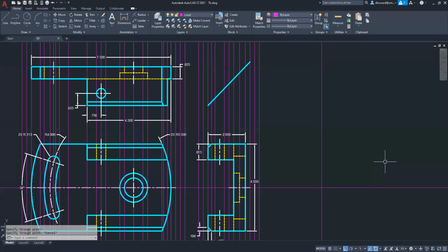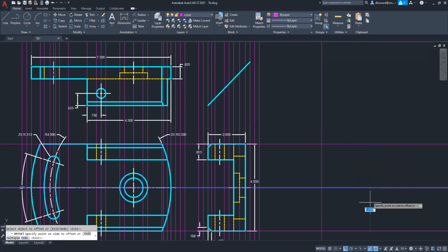Okay, so one of the first things you notice on the dimensions that they give us is they gave us the overall size, 7.5 by 4.5. So those are pretty obvious offsets to do. From the center going up is 2.25 and down 2.25. So we'll do that one. 2.25 from the center up and from the center down.